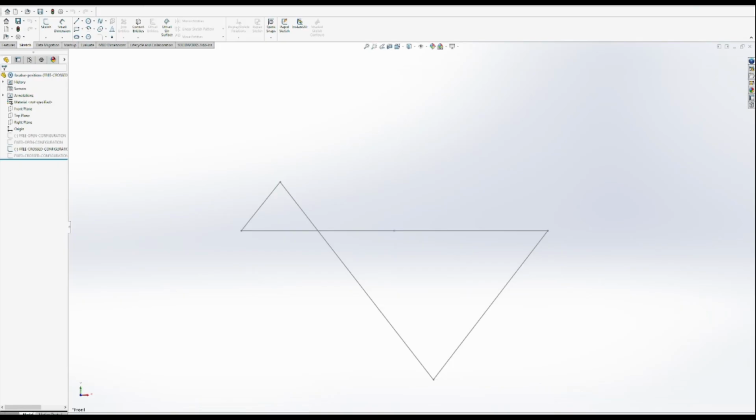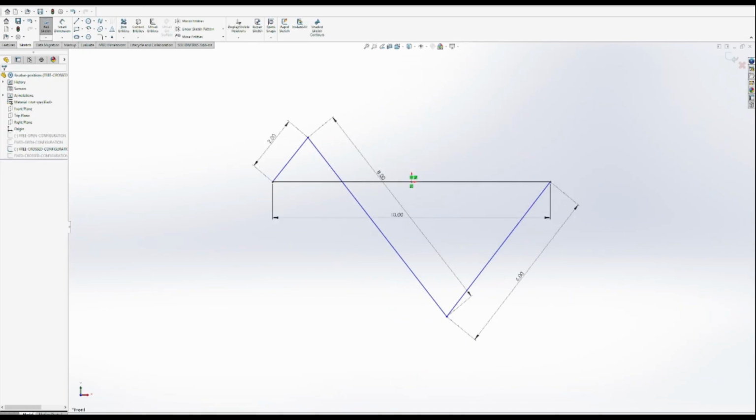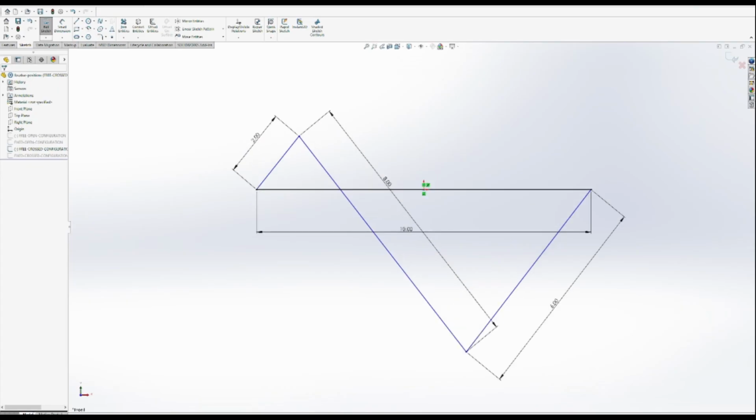Essentially, you're taking out this pin, disassembling this pin, and then reassembling the links in the only other position that they will reassemble at this theta 2. And it brings you from the open configuration to the cross configuration just like this. So let's go into this sketch, and now let's do a quick motion study here as well. So this is the cross configuration. It's just a different circuit of the same linkage.